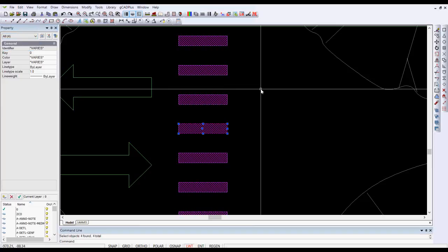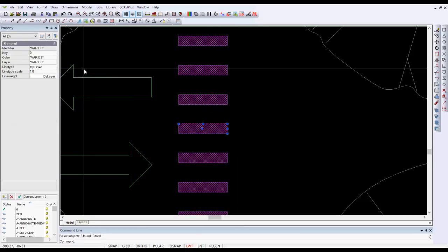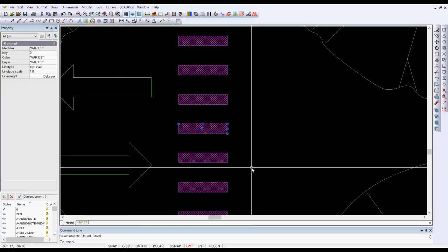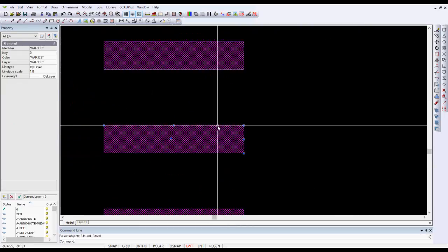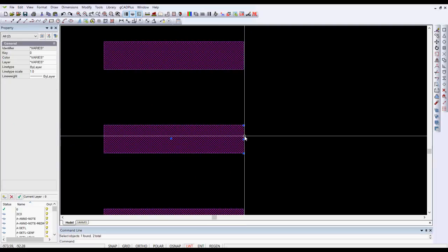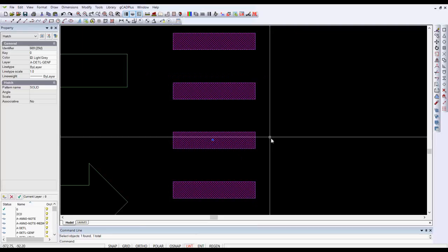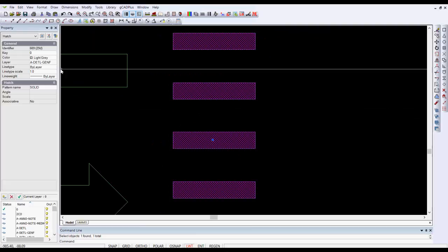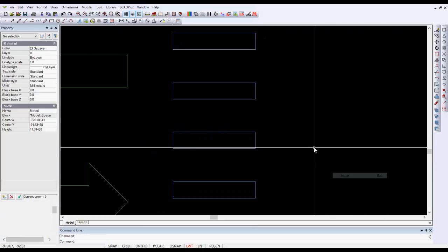So I want to find out just a little more about the hatch pattern first, so I select them in the same way, and now hold my shift key down and click on the lines that are selected, and that takes them out of the equation. So now the hatch pattern is located, and the hatch pattern has a light grey colour on a layer called DTL Gen F. So we can now erase them.